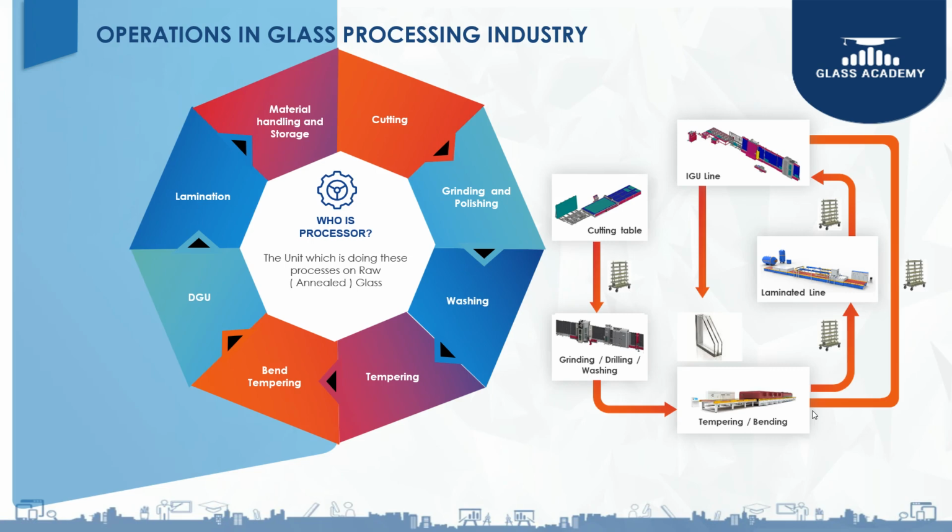Why are we doing this? Because once the glass goes inside the furnace, it will have thermal stress in the glass. That will create wear and tear at the edges. The simple property that we have is that wherever there is a sheet edge, there will be wear and tear at a higher rate. So to reduce that inside the furnace, we are doing all the glasses with it. So this is the basic principle. Whatever glass you want to do, toughened or HS, it should be rough grinded.